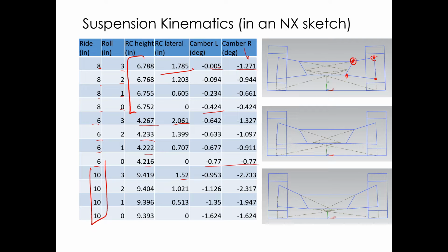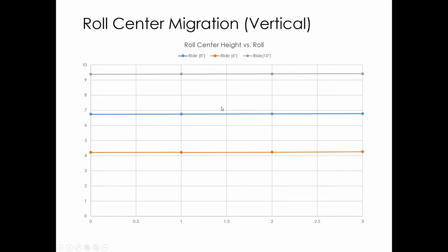So it's always going to be a compromise of your roll center and camber gain, and the other things like caster, and this will be kingpin inclination, and a whole lot of other complicated things that I could go into a whole other video on. But it's always going to be some kind of a compromise. But in general, you sort of want to start with getting your roll centers to behave, getting your camber to behave, and if you do that, and you don't do anything too weird with these points, if there's not too much inclination on this axis, things will behave fairly well, at least to get started with.